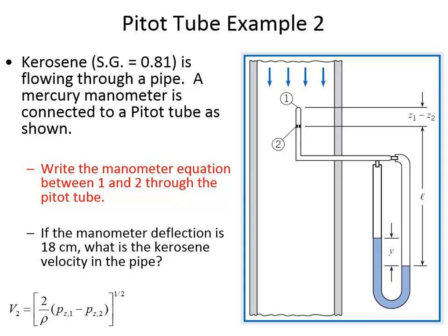So go through that process, and the route that you should take is starting at the opening at 1, you're going down through the pitot tube, and it goes to this side. The pressure is greater here, and this is a reflection of what the pressure is at 1. And then you're going up now through it, and you're at 2.